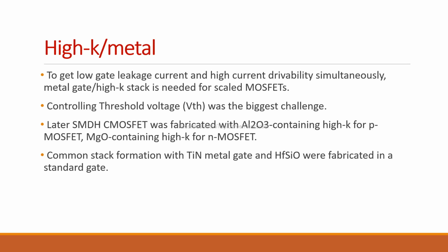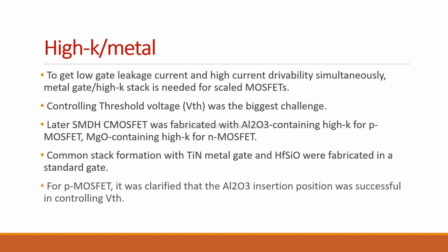A common stack formation with TiN metal gate and HfSiO was fabricated in a standard gate. For the P MOSFET, it was clarified that the Al2O3 insertion position was successful in controlling the threshold voltage. So next, the limits will be explained by Akash.